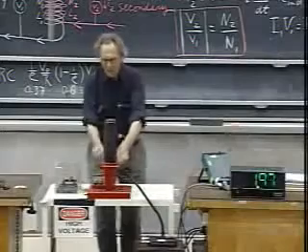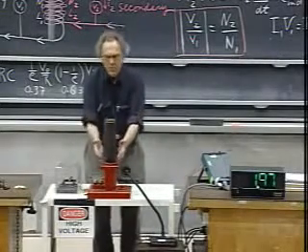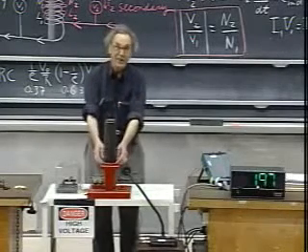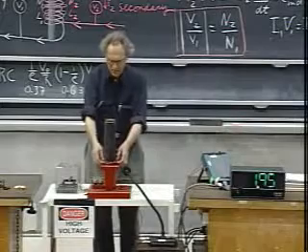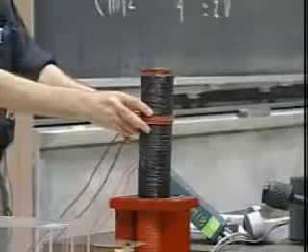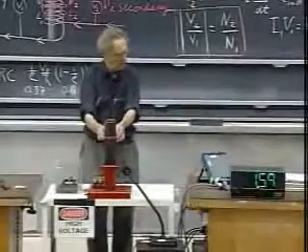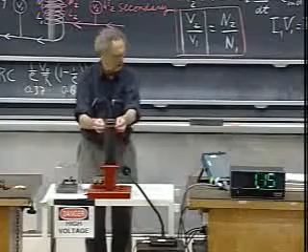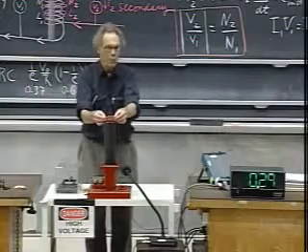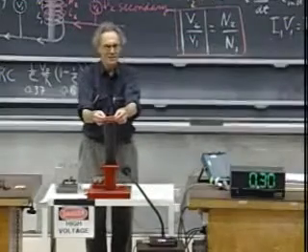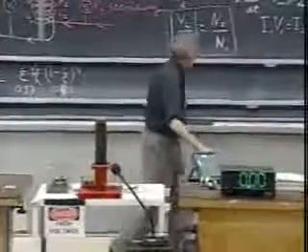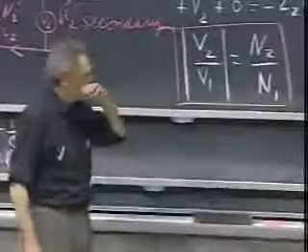What I will do now, I will move it up a little. And when I move it up a little, the flux coupling of the secondary is not ideal anymore. And so you expect that V2 will go down. Just move it up a little along the primary, and you see the value goes down. Because now the flux coupling is not ideal. And if I bring it further out, the flux coupling becomes hopeless, and when I bring it here, the flux coupling is so poor, but I still get 0.3 volts, by the way. So that's the first part, to show you that this is indeed quite accurate.